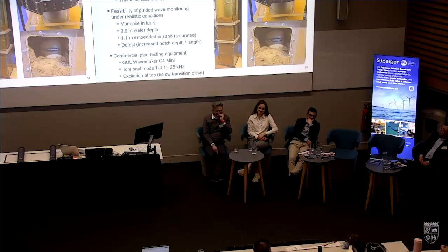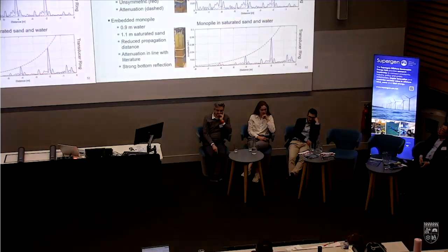We filled it with water, and we had an access hatch here at the side where we could pump out the water, take away some of the sand, introduce an artificial defect at one of the weld locations, and then basically close everything back up and do a measurement with these ultrasonic waves, where we borrowed some commercial pipe testing equipment, which we fixed above the water level, roughly where the transition piece would be in a real monopile. And then we did some measurements on this.